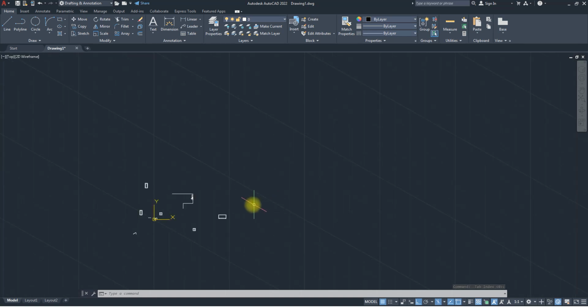Okay, exactly. Try line. Yes. So if I create a line now and make sure my Ortho is on, click, it goes vertical, right? Okay, normal one. But if I come down, it's not going horizontal, it's following that grid pattern, the grid line. So this is to let you know that this is not going vertical or horizontal, it's following the grid line. Do you understand?